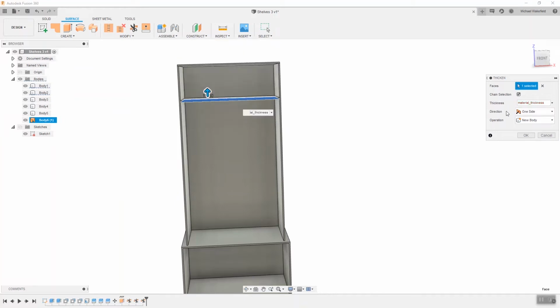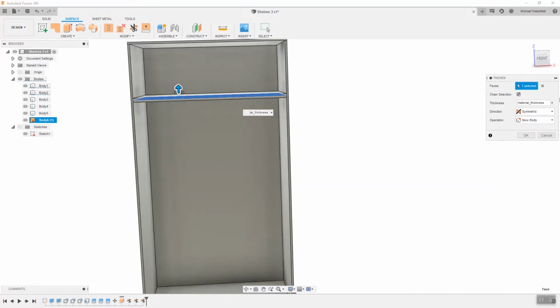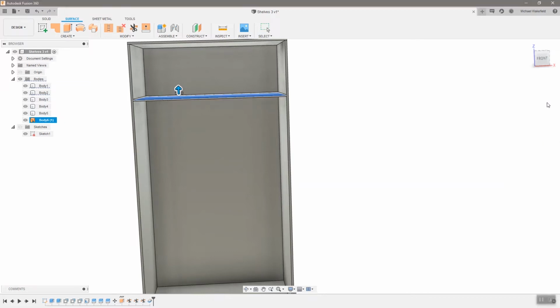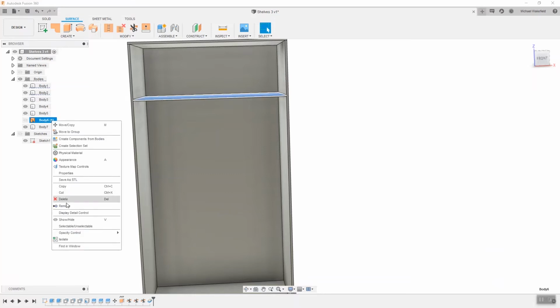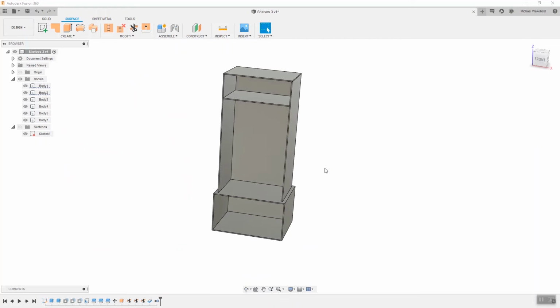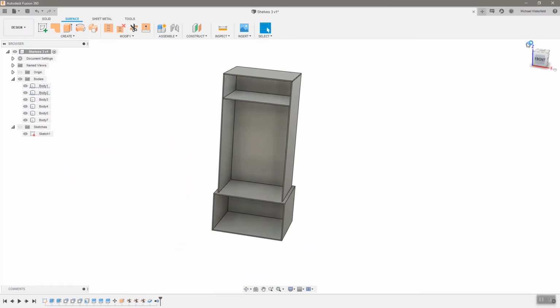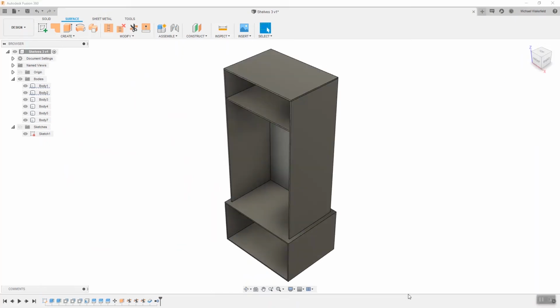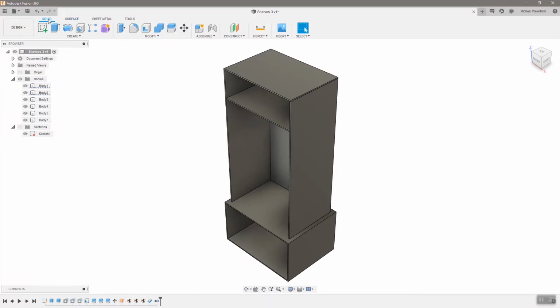And here again, I'm going to use my material thickness parameter that I created. But I'm going to do symmetry. I'm going to do it on both sides so that middle surface is actually in the middle. And that unfortunately will make it double thickness. So I have to take material thickness and divide that by 2. Once that's done, there's no need for that surface. So I can use the remove command to actually remove that surface that I created in order to create this body. And it gets out of my tree, and it's very simple that way.